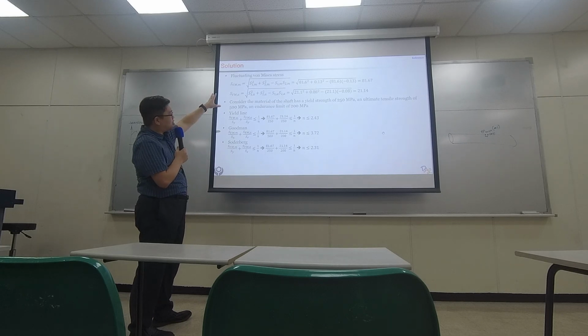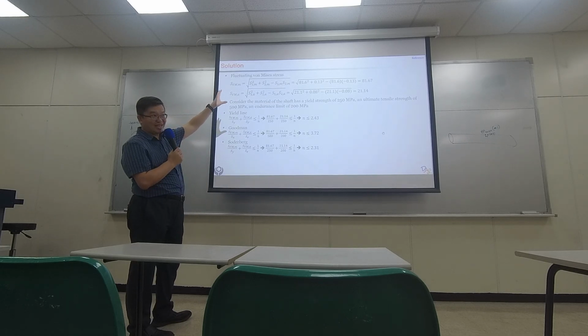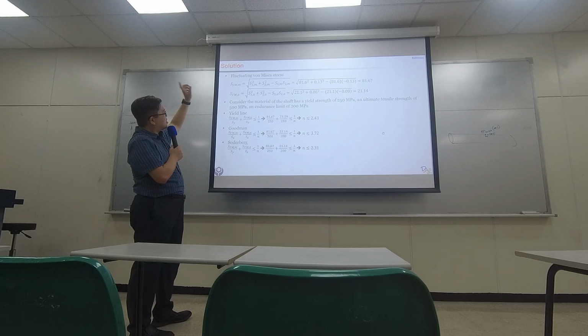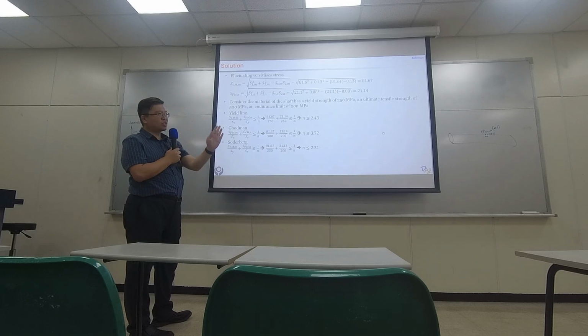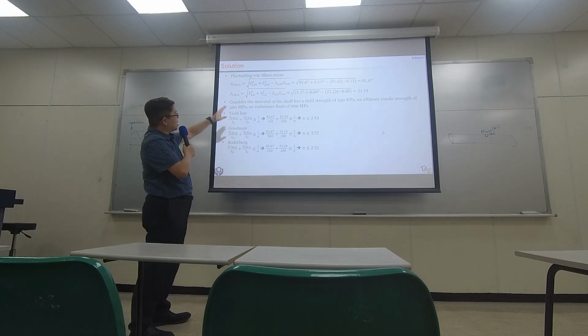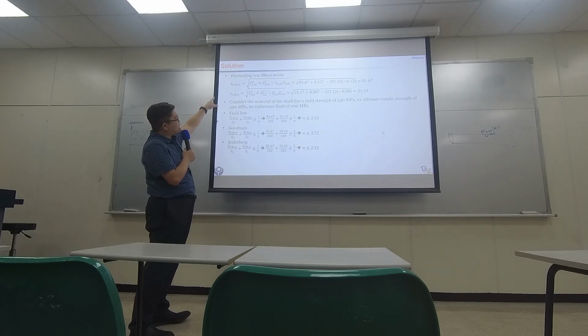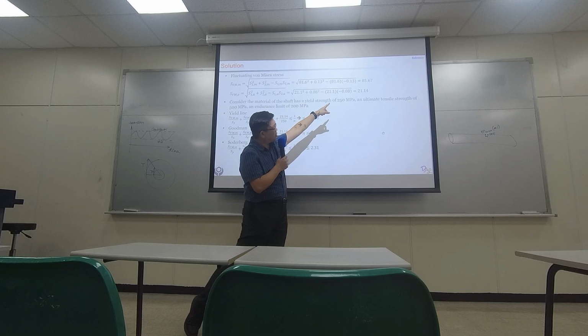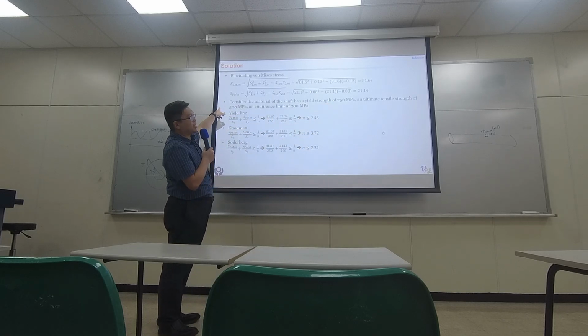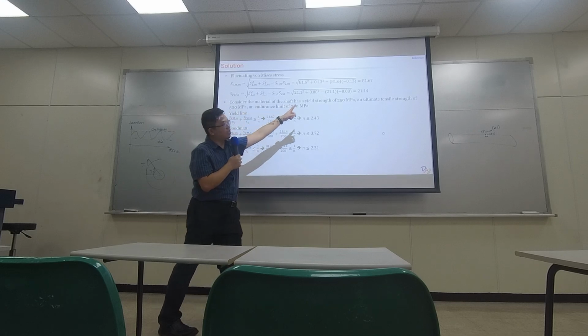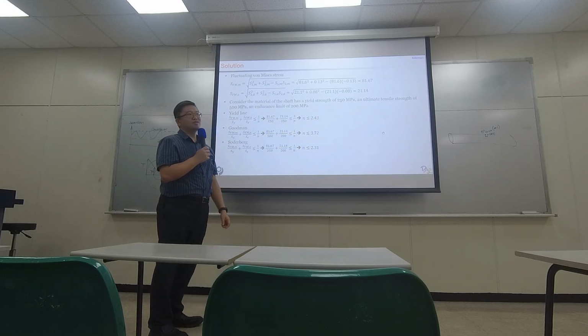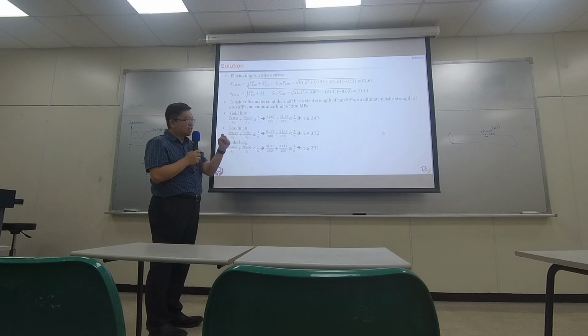So overall, equivalently, the worst loading area has a mean value of von Mises stress of 81 megapascal, plus or minus the amplitude, 21 megapascal. Okay, so that's the